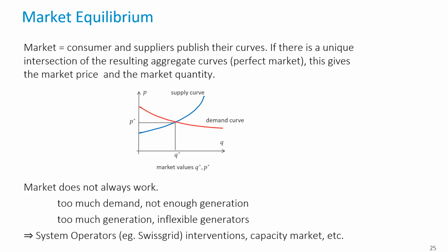And in addition to that, you have a capacity market for the reserves, and you also have secondary versus tertiary reserves, where in the case of tertiary reserves, operators are paid simply for having the capacity. In the case of secondary reserve, operators are paid for both the capacity and their usage and how much energy they have produced. So all of this together is the global picture of the energy provision today.